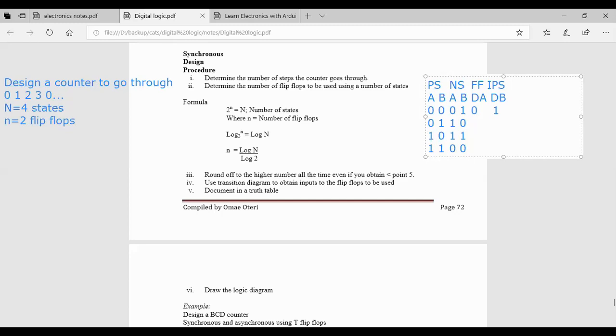Now let's look at the next one. This is 0A, 1A. So 1 present state, 0, 1, 0 present state, 1 next state. What should be DA? One. Should be 1 because 0 to 1 is 1. Anyway, let me do for D all of them, first of all. So 1 to 1 for D? One. Should be 1, that's correct. 1 to 0, what is D? 0. That's correct.